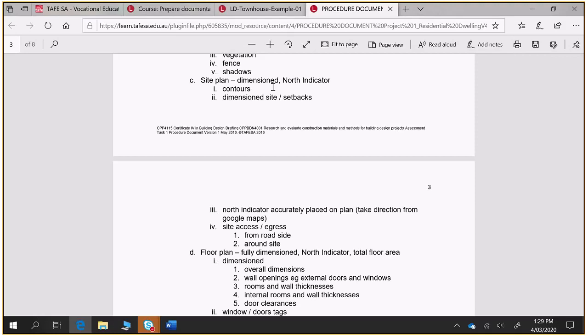We don't want to go putting a third one on there, because if the fences aren't where we've said the boundary is, and there are issues like that, we might get people dimensioning off here instead, and other people dimensioning off here, and there being a discrepancy somewhere in there. A room in the middle of the house could be half the size, or the concrete slab isn't meeting up. So always try not to put too much information on. Just think, okay, have I provided enough information for people to get to an answer? Yes? All right. Step back.